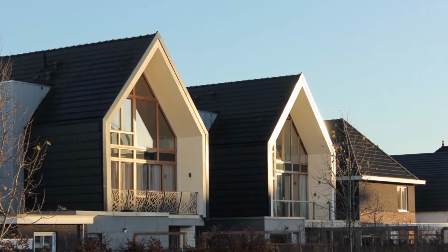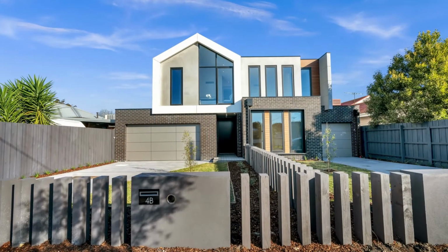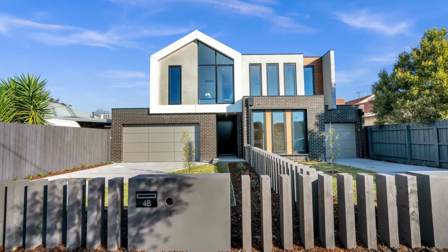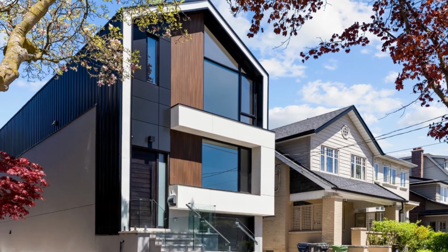Tip number 2 is a simpler building form. There's a spectrum of complexity from a boxy bunker to the palace at Versailles, and everything in between. You can have a straight wall that construction-wise is very simple to build, but you move in and out the exterior finishes. The roofs, a lot of the time, will jog up and down. They'll have dormers that you don't even see from the inside. They're very costly to build and really are there just for some visual aesthetic.